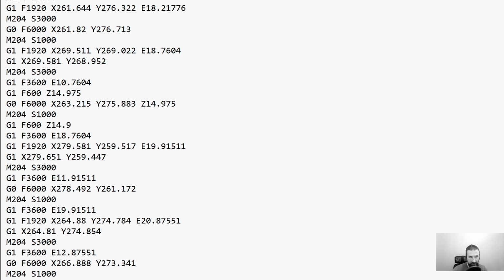There are some specialties. Some machines, normally CNC machines, also support arc commands, so you can create circular motions without defining a lot of points for that. But this is normally not used in 3D printing. I did not see any slicer doing that. Normally a slicer creates any circle by just creating a bunch of points on that circle.